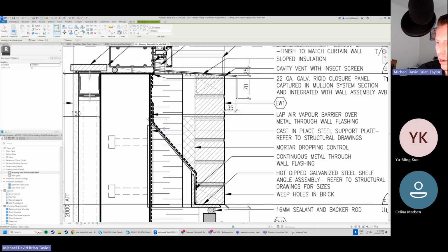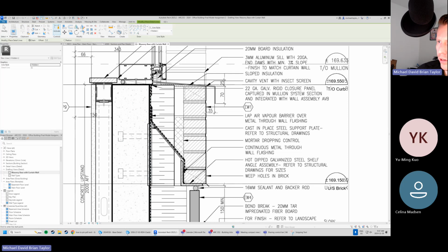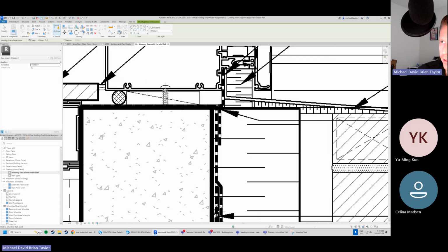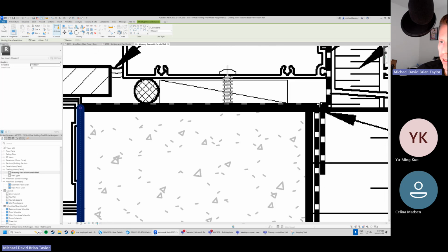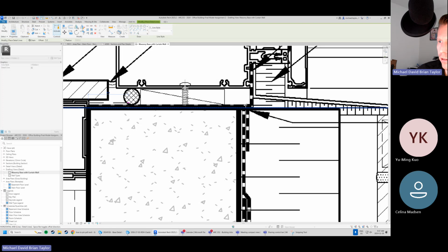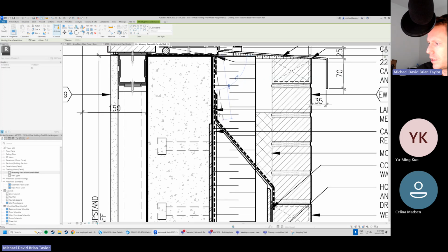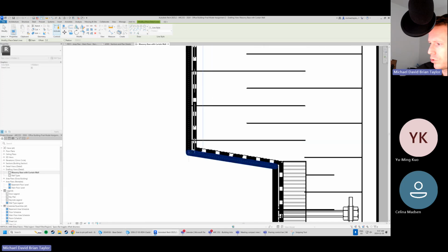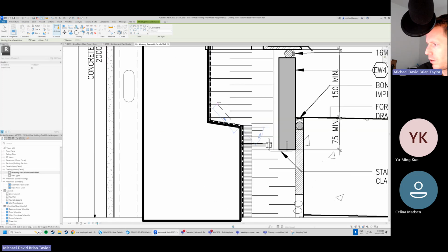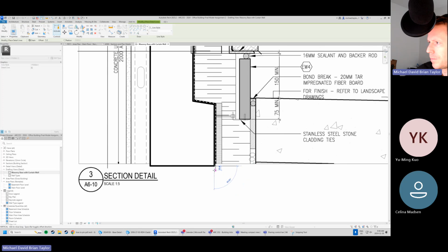And now because we've got our concrete kind of started, if I take a line here and you see this little chain here, I got the chain on and I'm going to click once. And when I start to draw, if you remember this from previous classes, I've got that 5 mm offset from the thing that I'm drawing on. So this can be really effective for when we're drawing things like membranes. And if it's chained, I'm just going to keep drawing here. I'm going to draw us all the way down here and trace this line. Keep going here, all the way to the bottom.